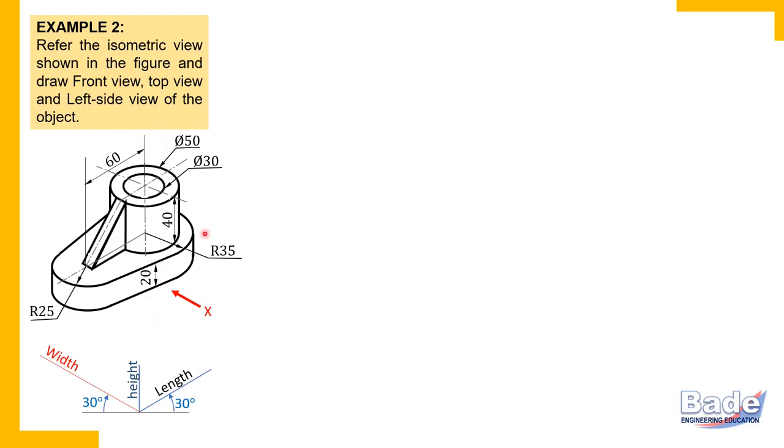Do you remember? We have studied in the first video. So front, back, left, right, top and bottom. So the left edge is a curved edge, the right edge is a curved edge. When circular edges are at the end, then generally distances are given between their centers. So from the center of this curved edge and from the center of this curved edge, which has radius 35, watch here, it is mentioned here, from this point, center to center distance is 60 millimeters.